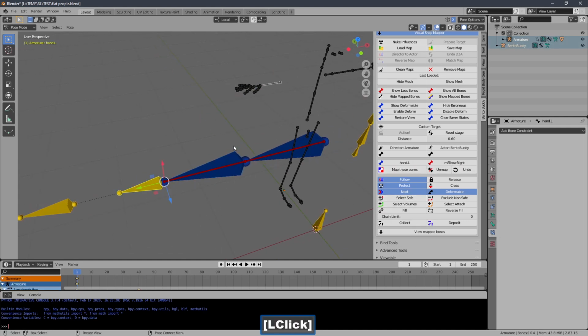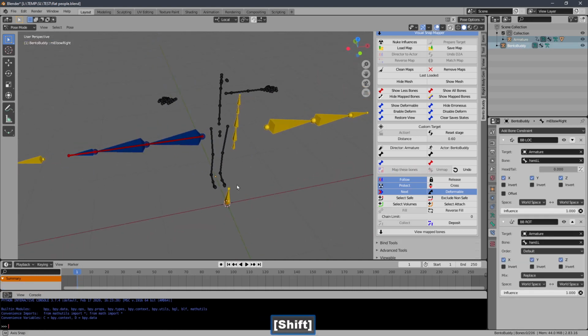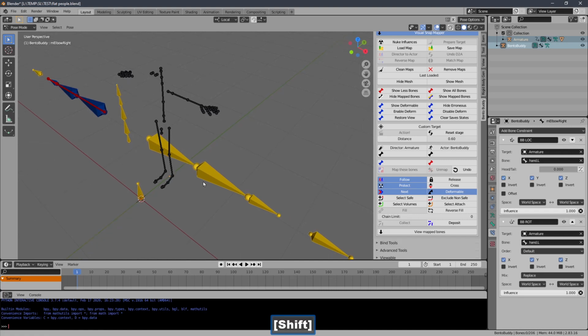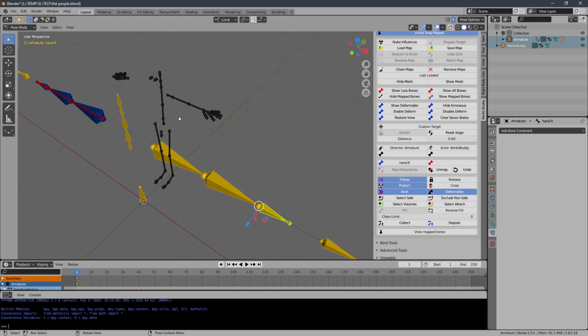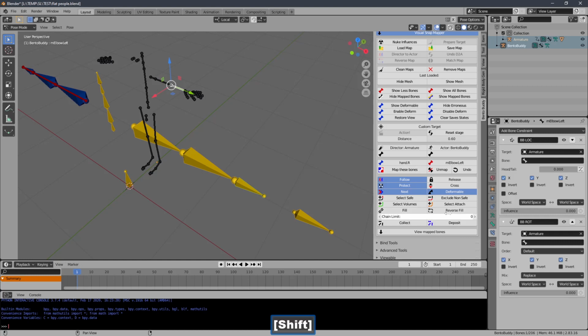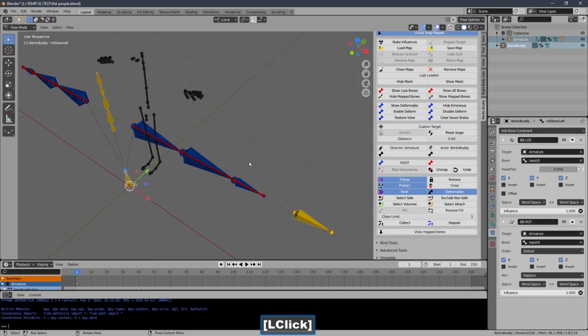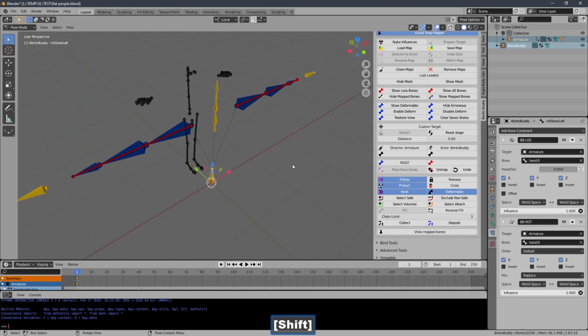And we're done at that particular point, but if you had fingers, you'd do those as well. And the fill tool will help you with this, with the hands when you get to the fingers. So I'm going to select the end bone on this one, and I know there are 3, 1, 2, 3, so I count backwards, 1, 2, 3, and then I choose how many to fill with, and that's 3, and click the fill tool. Now I've got those. So now these are mapped.